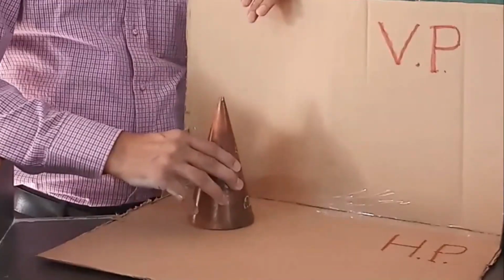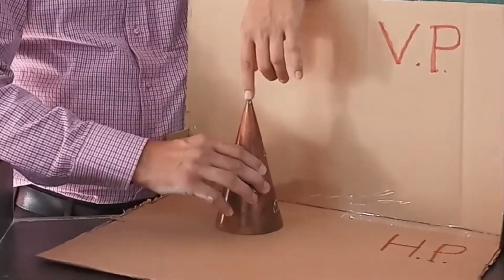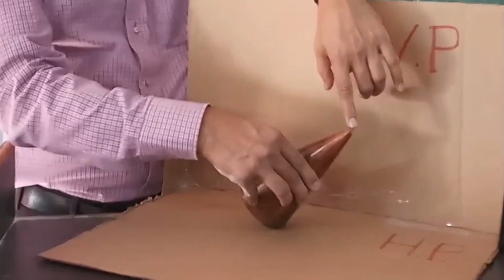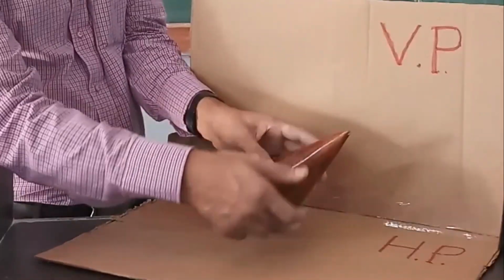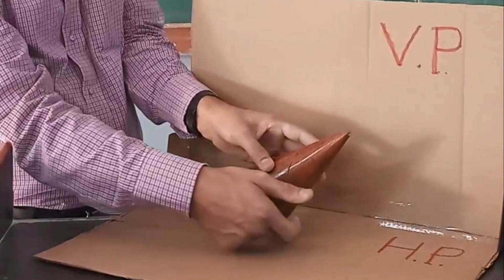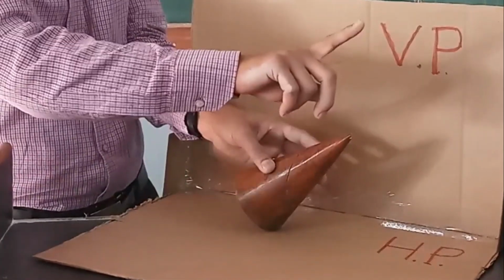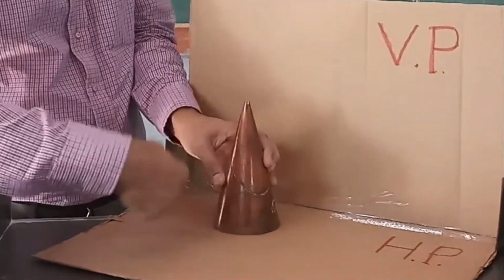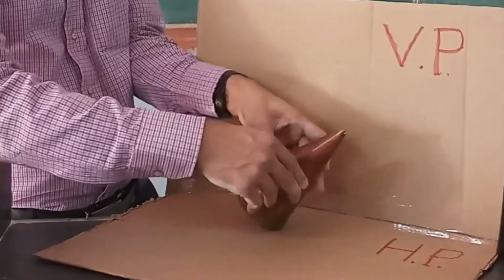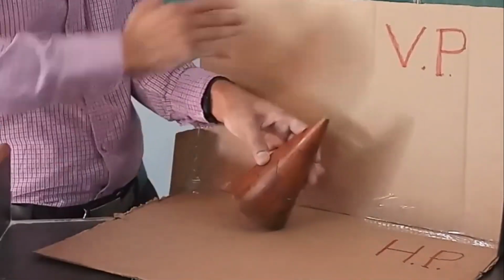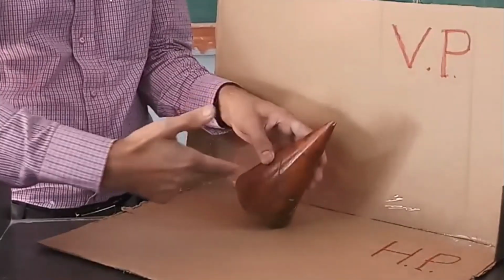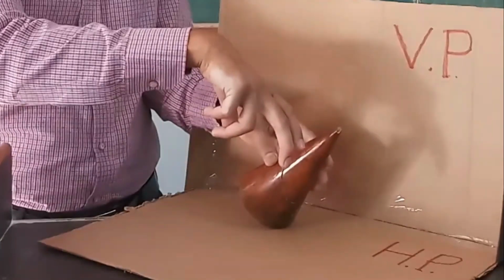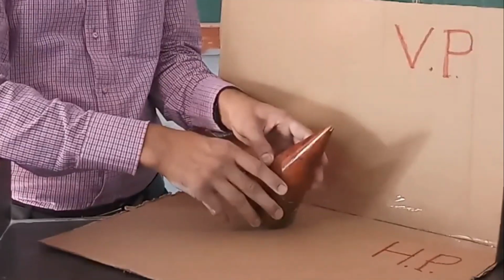Now after this we have to incline this cone such that the axis now makes 30° with horizontal plane. So if I tilt it something like this, it is now resting on one corner, one point of its circumference, and at the same time axis is also making 30° with horizontal plane. So we observe here that the initial front view, which is a triangle, is now getting tilted at certain angle. So we have to reproduce front view such that the axis now makes 30° with horizontal plane. So after reproducing front view, from that we can draw its top view. Let us see how to draw projections of this solid.